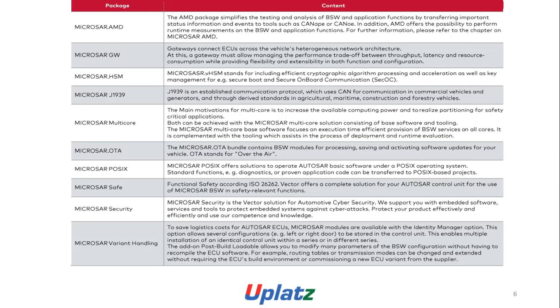The add-on post-build loadable allows you to modify many parameters of the BSW configuration without having to recompile the ECU software. For example, routing tables or transmission module modes can be changed and extended without requiring the ECU build environment or commissioning a new ECU variant from the supplier.